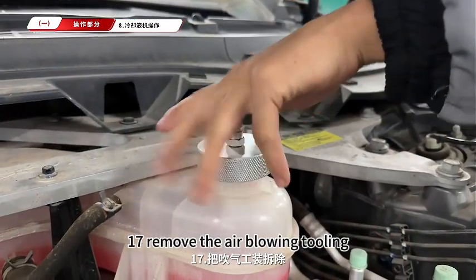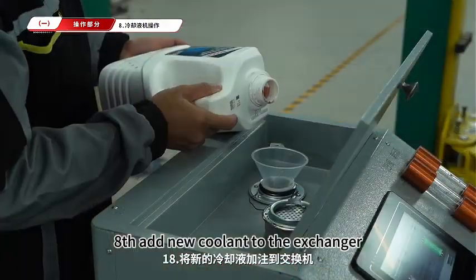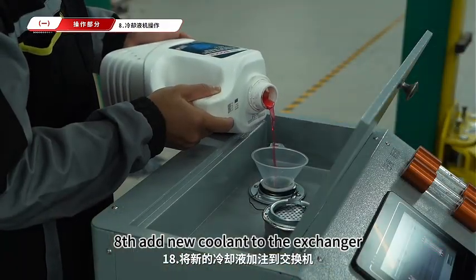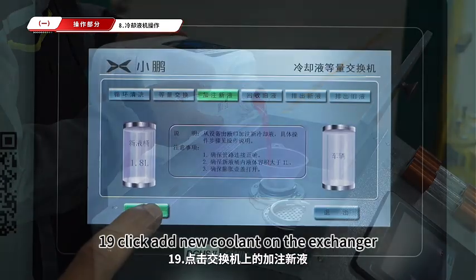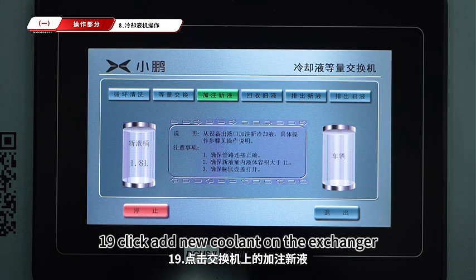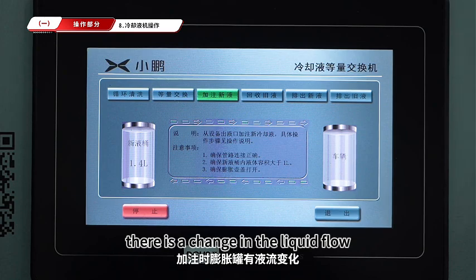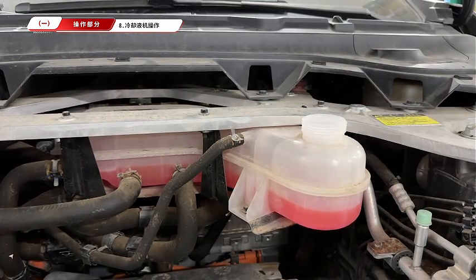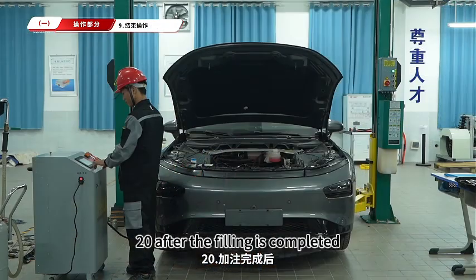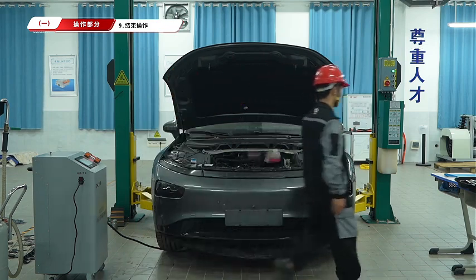Seventeenth, remove the air-blowing tooling. Eighteenth, add new coolant to the exchanger. Nineteenth, click Add new coolant on the exchanger. When new liquid is added, there is a change in the liquid flow. Twentieth, after the filling is completed, turn off the exchanger.